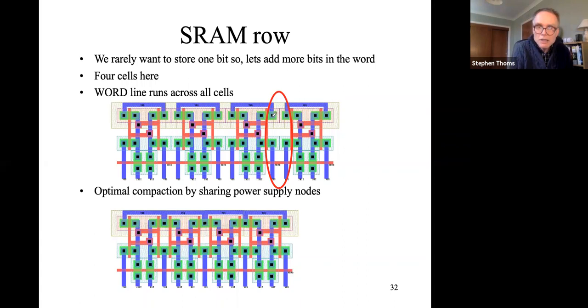You're not saving a lot of space, but you're saving a little bit of space per bit, and you might have thousands of millions of these SRAM cells in your final chip. So although you might only be saving, say, 10% of the space per individual cell, multiplied over millions of cells, this becomes a significant saving. So sometimes, just looking at the circuit, human tweaking can be useful.